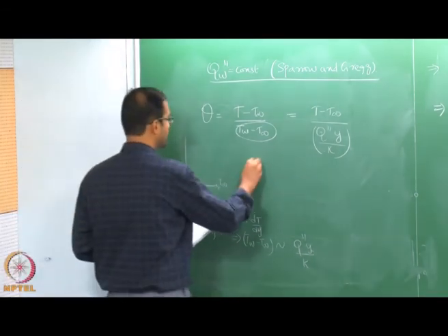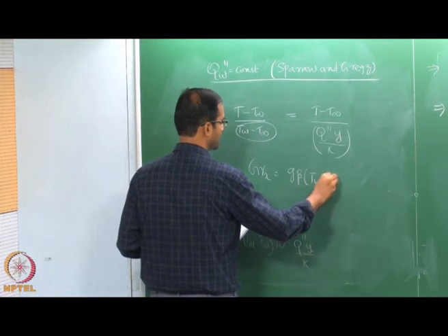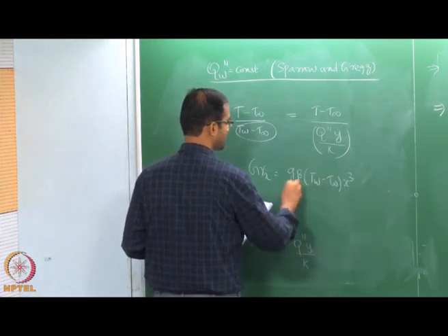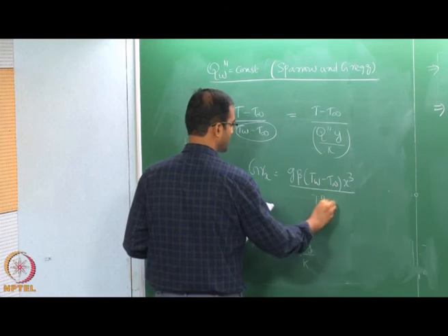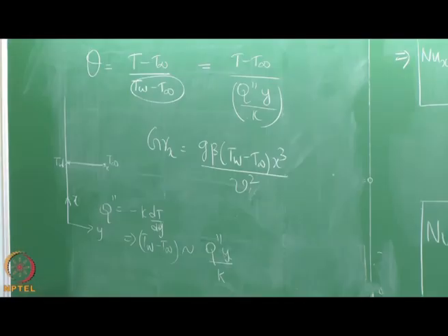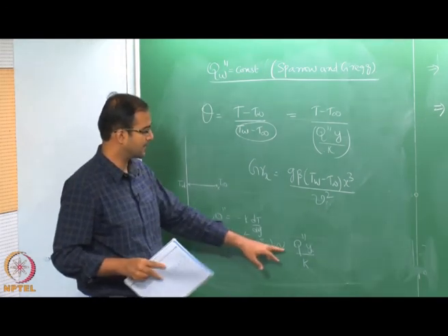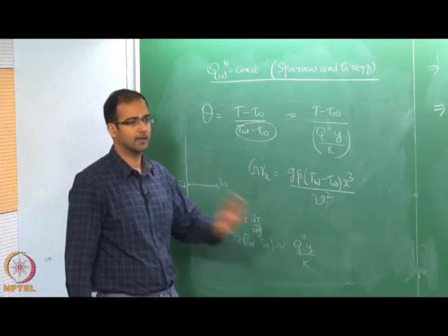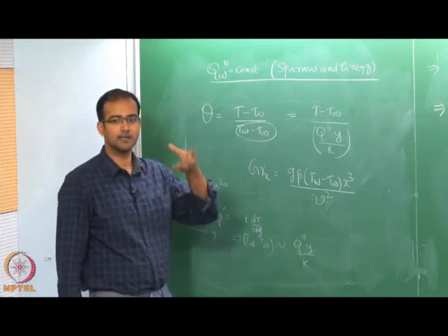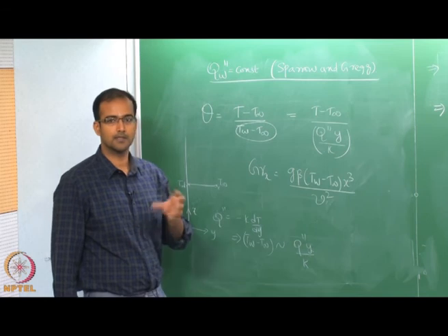So, your conventional definition of Grashof number is also based on temperature differences. Now, how do we convert this temperature difference into what is known to us in terms of heat flux? Again we will use a similar scaling. So, we can simply write T wall minus T infinity as something like q double prime x by k. The order of magnitude of x and y are comparable now, so we will just interchange them.